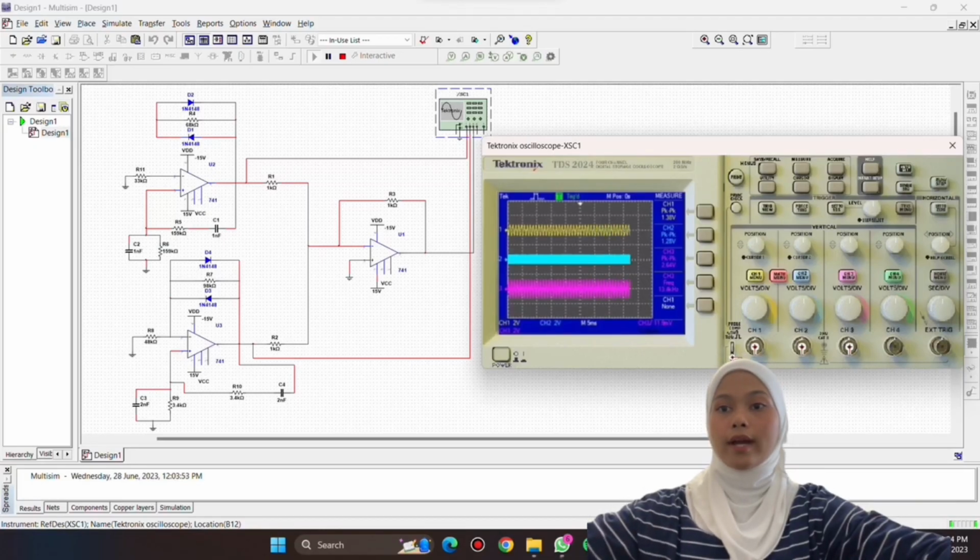Here is oscillator 1, Wien bridge. Oscillator 2, Wien bridge. The output of the summing amplifier is channel 1 V peak to peak, channel 2 V peak to peak. So divide it, as you can see in the calculation, we get 1.322 volt, which is near to the exact value from the calculation. That's all. We will continue to my other friend.